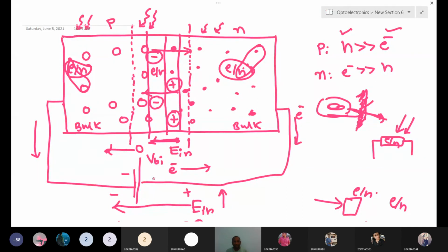Because of this attraction of charge carriers, more electrons leave this place, more positive charge is developed and more negative charge is induced in the depletion region. Because of this increased charge density, negative and positive, in the depletion region, the internal electric field is increased.